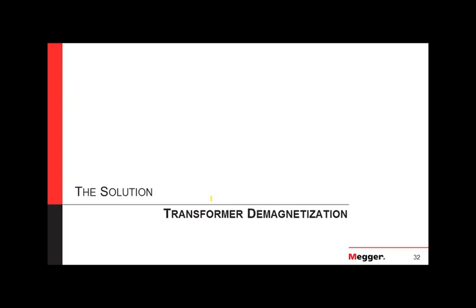As I was telling you, the external legs on a core type transformer are symmetrical because the length of the flux path is basically the same, as compared to the central leg in your transformer. So these two external legs, your phase A and phase C, will have very similar excitation current values.